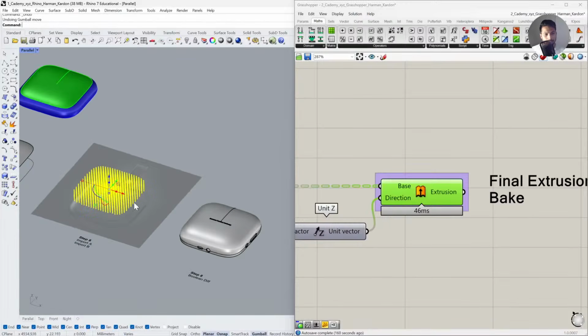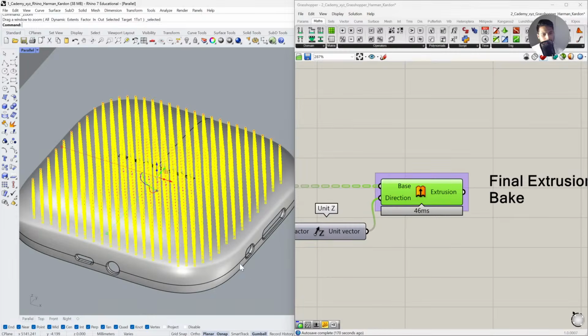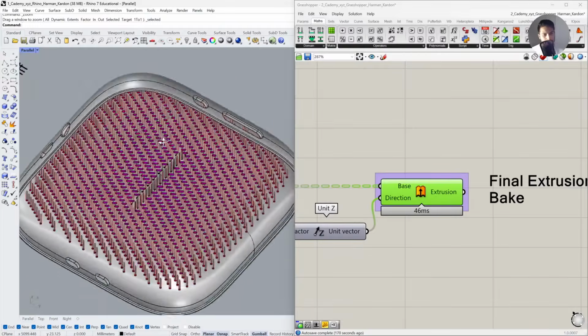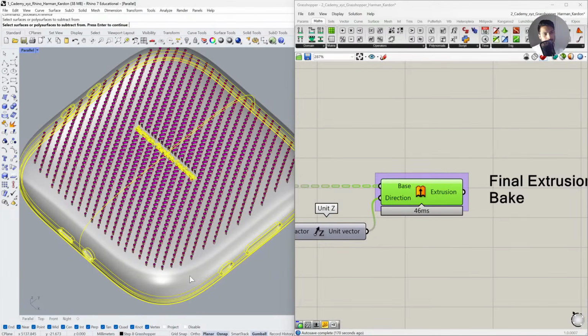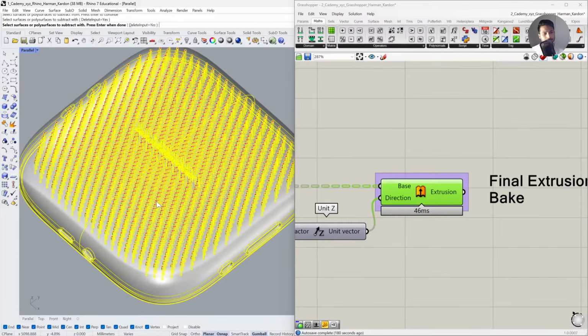Okay, now there is a fixed gap between all the steps. I think it's 200 units, so you can move it by 200 units, and then you can perform a Boolean difference between this using these. A lot of times you will notice that I'm performing Boolean operations in Rhino, and that's a common approach because Grasshopper is quite slow when it comes to Boolean operations using the native components.